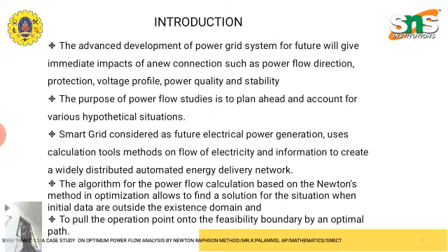The optimal reactive power dispatch problem, as a sub-problem of the OPF, is a very important optimization problem in power systems, as proper management of reactive power injection into the system can minimize real power loss and voltage profile deviations and improve voltage stability.